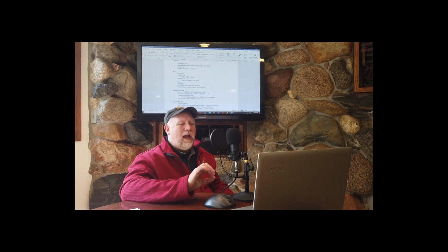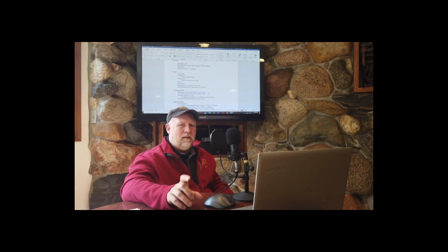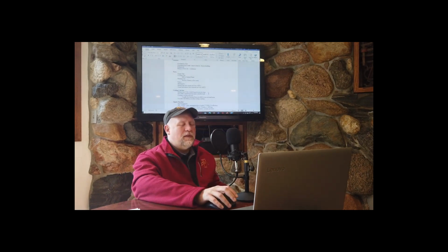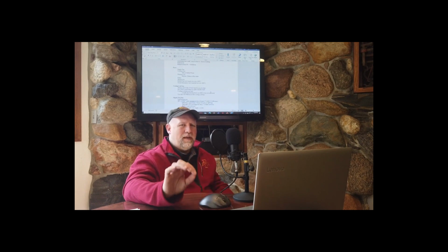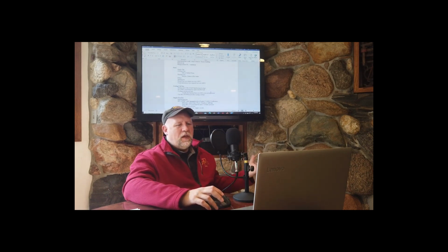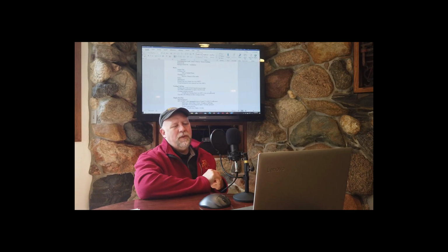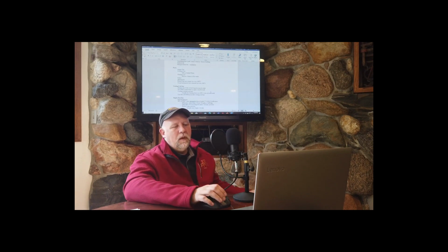The supply air CFM, once again, review from previous in this class, supply air CFM is based on space sensible load. Space sensible. Remember the 1.08 CFM delta T, where the Q is the space total sensible load, and that's how we size the supply air quantity, and therefore the supply air fan.